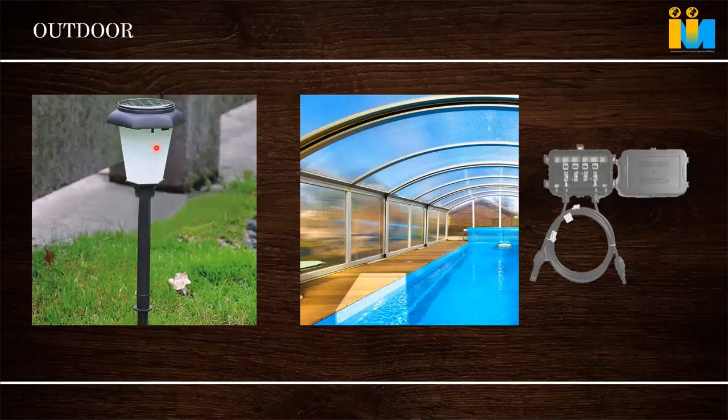So for the diffusion effect, diffusive additives are added to the polymer itself. It's a little bit costly. It is available, milky. It's not normal, we are adding a master batch. There are two properties to a diffusive material. One is transmittance, the other is diffusion. Normally, whenever the diffusion increases, transmittance will reduce. So a diffuser material has a combined property. Both properties together make it a challenging application compared to a normal material. And over and above this, it has outdoor exposure.